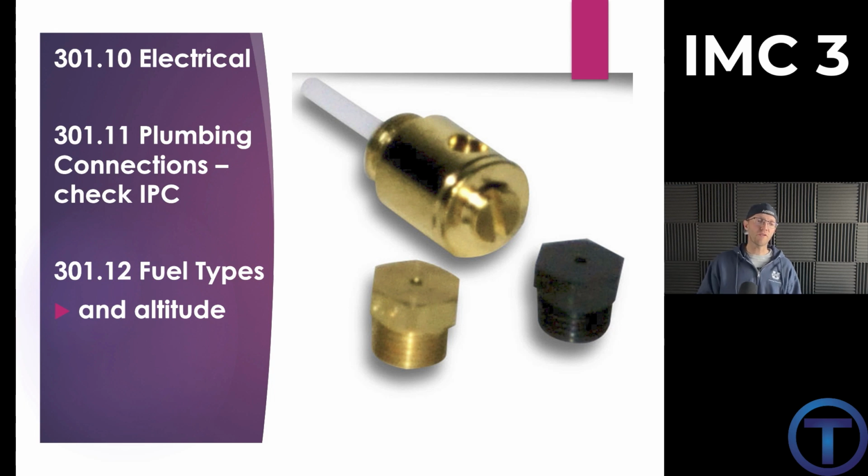And that has to do with orifices, and that's why you can see right here on this screen, these are orifices. They're just like a bushing that you can thread into the gas system. The orifice is what allows gas right out at the burn point, where it's going to hit the burner and spread out and be burned. And the rate at which that gas moves through or comes into the burner is really important.